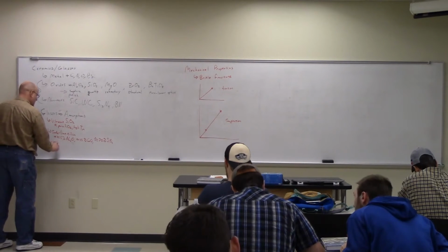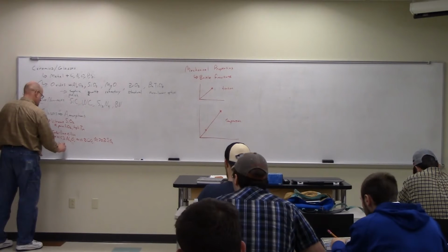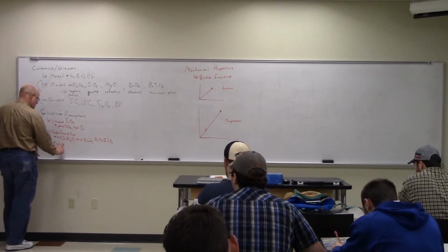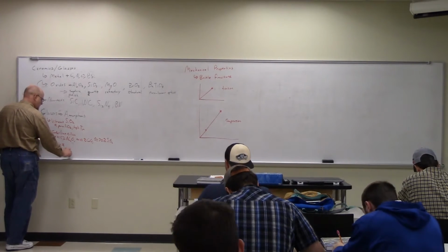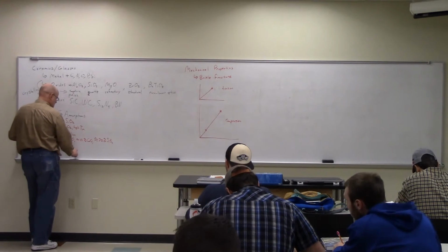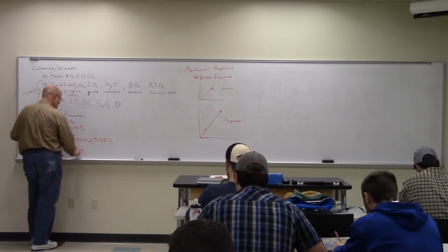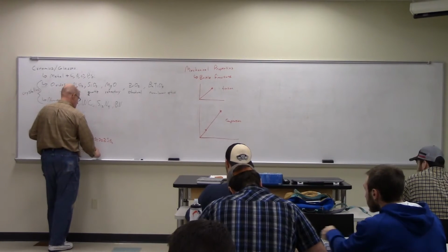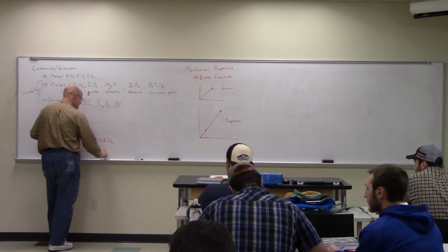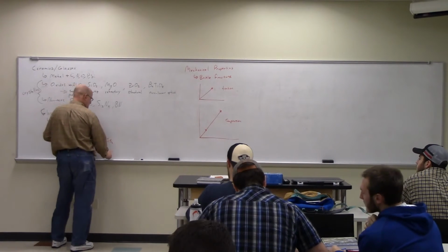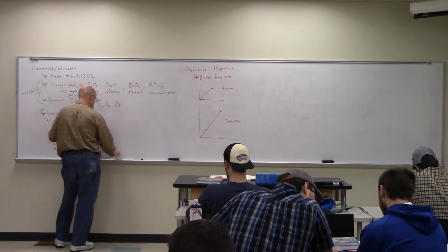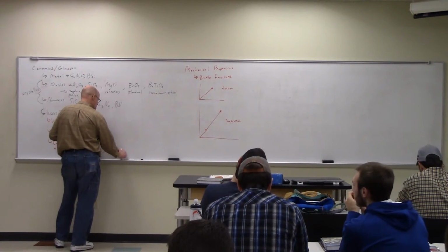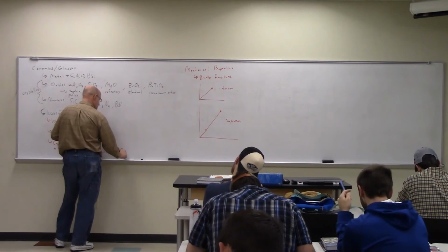Next is E-glass. Which is, getting down to the bottom of the board here, but on the order of 55% silica, 22% soda, 15% alumina, and on the order of 8% borate, B2O3.